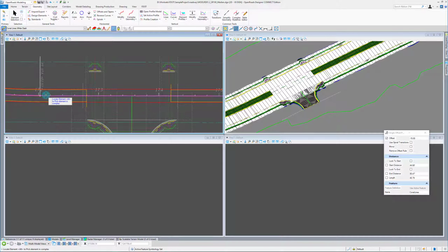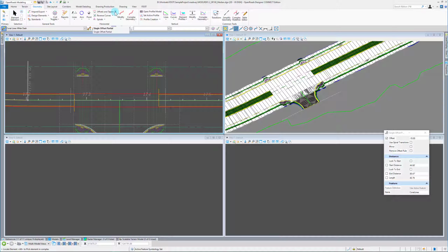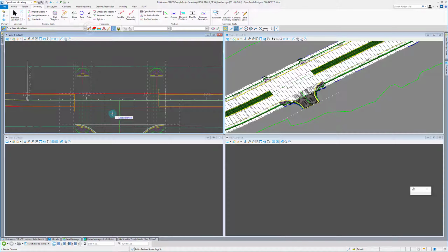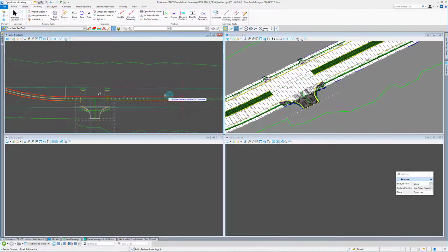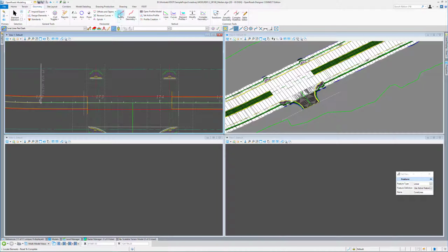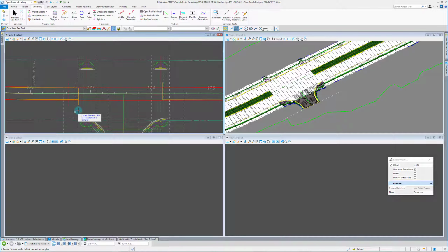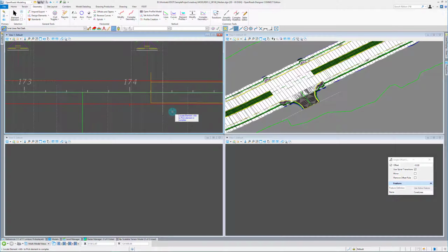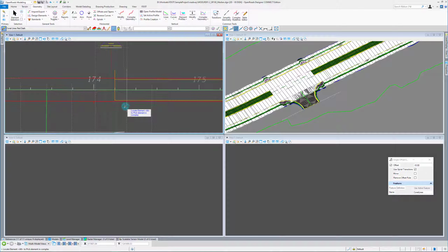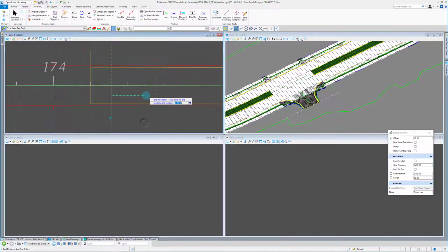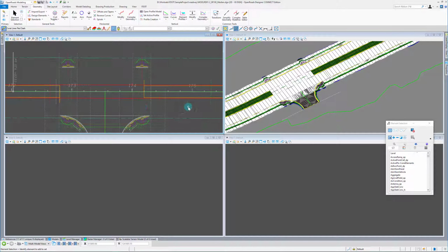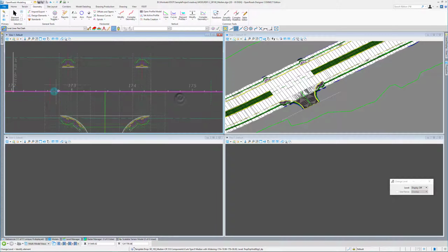So that'll be that line, and then I actually want to make my boundary elements red. That makes a lot more sense to me. So let's set the feature definition of this one to red. And I'm going to offset this 10. Okay. So that's going to go there. I want to offset this just on this side though for 10. And I'm going to turn off this median corridor lines here.